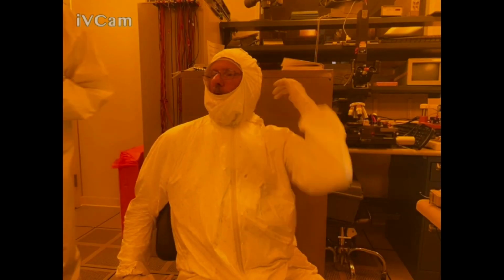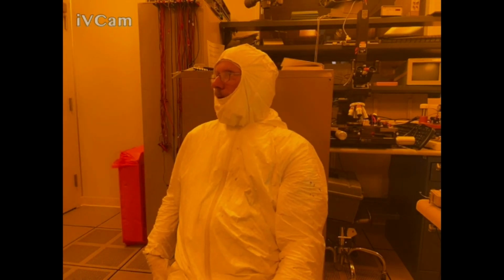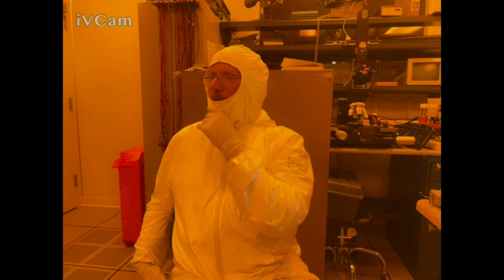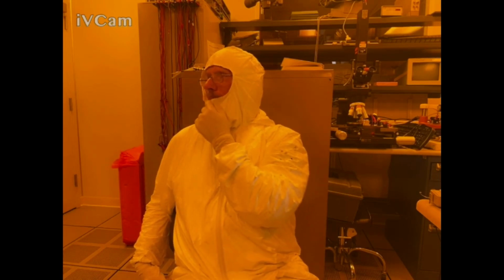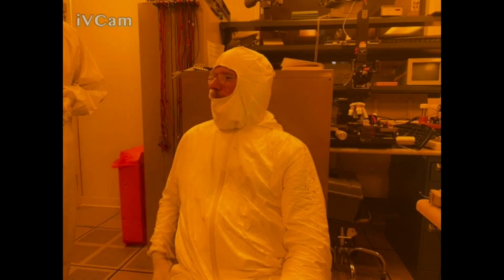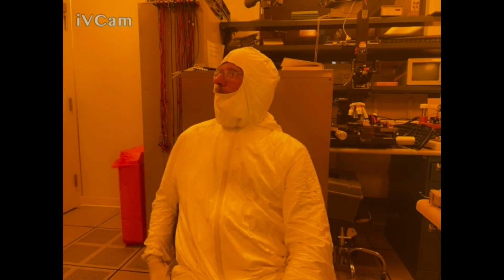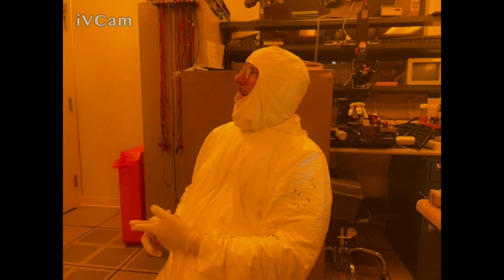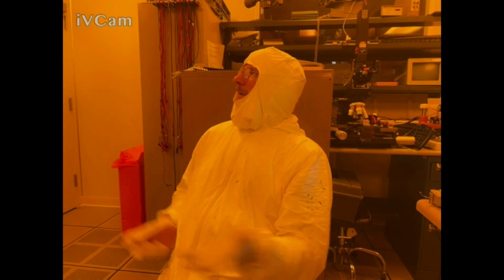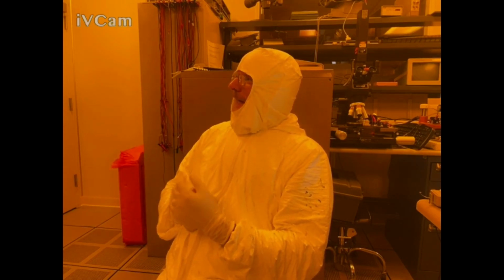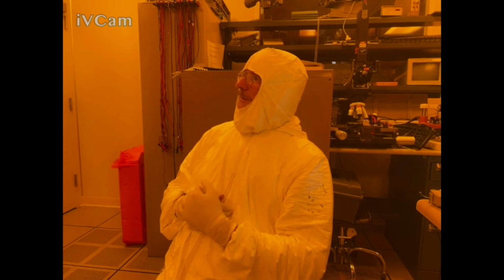Every CV meter has a sweet spot. Ours is 1 megahertz. That's just where it works the best. You're going to find that with any CV meter because they're not all going to work the same at different frequencies. Most of them run at 1 megahertz. Now we could change that, or we could do a frequency sweep. We could run capacitance, but not on a MOSFET. For a MOSCap, you can do a frequency sweep.